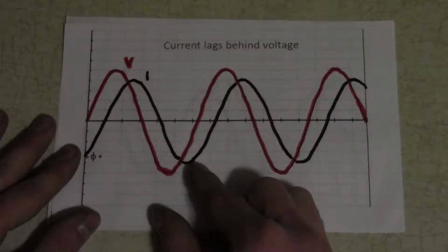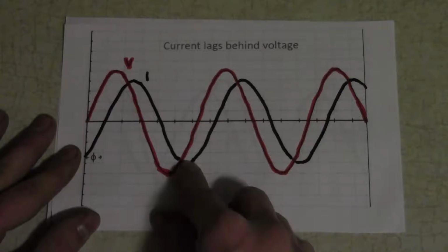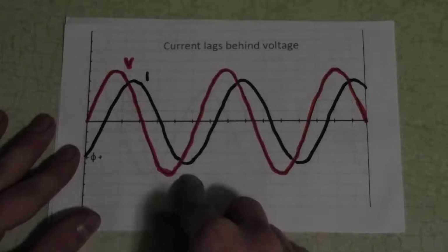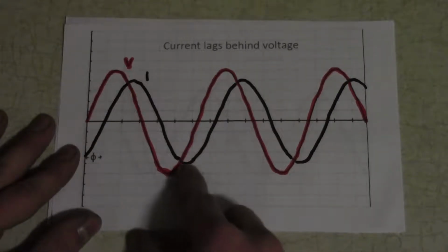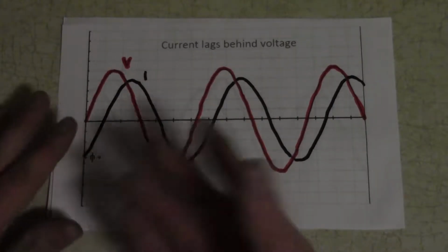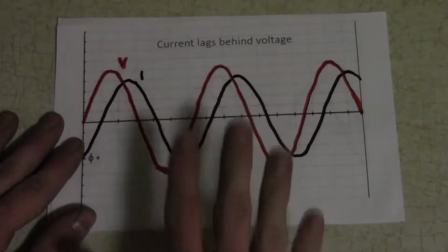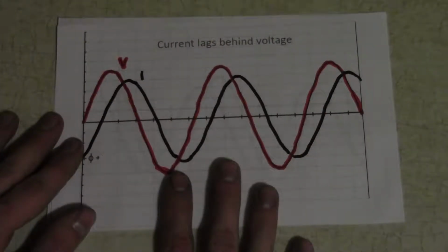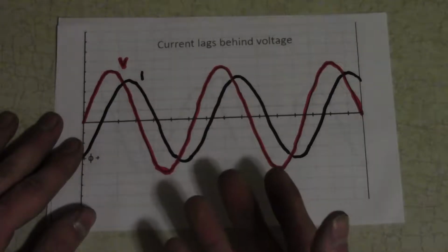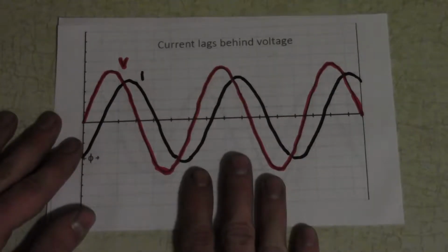And actually, when we hook up my truck, we will find out how the power factor affects the current, because I believe it does. I believe it actually increases the current. But either way, whether it increases the amplitude of this wave or not, the effect is, with this out of phase, this puts an increased demand on your power supply, whether you're getting your power from a power company or, in my case, a generator on my truck. So this is why it's important.